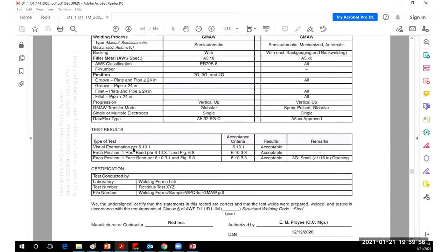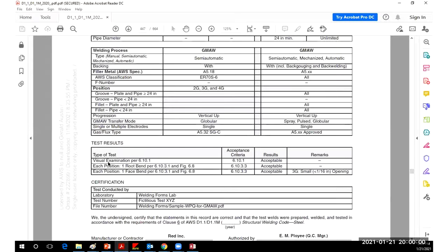Here's when I fill out the welder performance qualification test record, the type of test, I'll refer to the specific paragraph, the figure number, that type of stuff. That way there's a clear record of what I did. Here's a case where somebody put in discontinuity that was in the bend test. It's not required to be there. You can make remarks if you want to, but there's no requirement. But I do have to record whether they're acceptable or not.